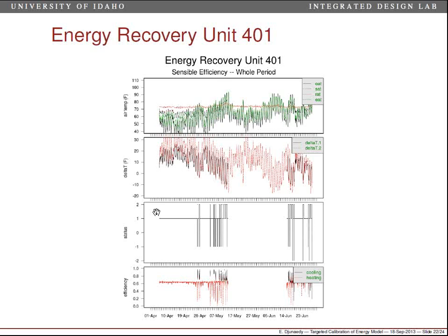It happens, unless the logger is messed up. But it happens. There is this -1 status. There is a -2 status, where it should be in cooling mode, but it heats the air. It works the opposite. And when I say it should be in cooling mode, it means that the return air is lower than the outside air. In heating mode, the return air is higher than the outside air. This is not spelled out in the manual of the heat recovery system. But this will never happen in the simulation world. And we need to figure out how to capture this.